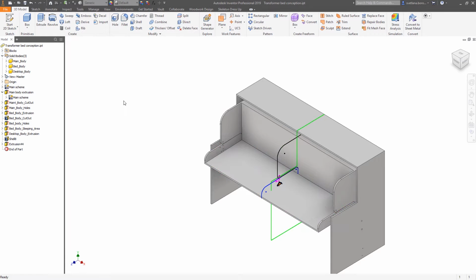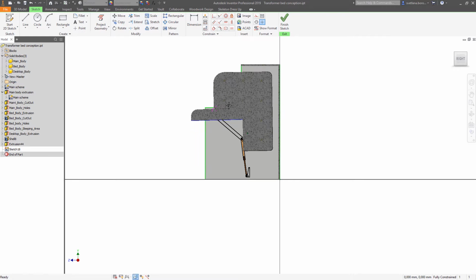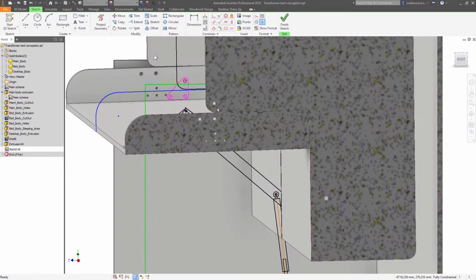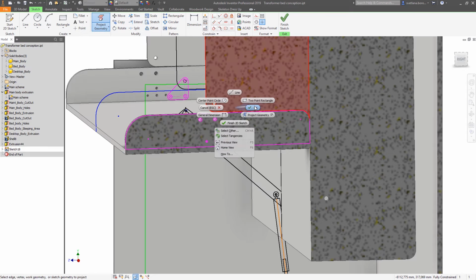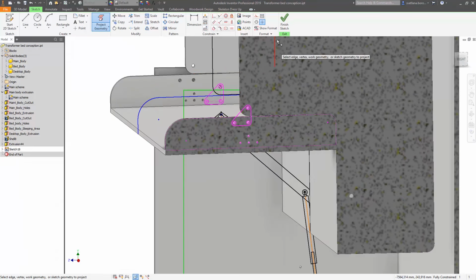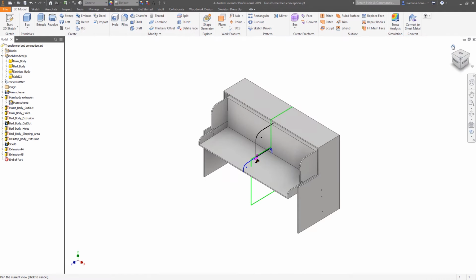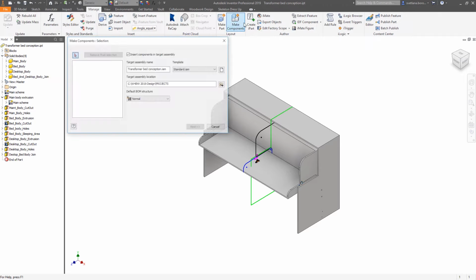reference geometry. And now we can use our sketch, project the geometry of joining item, joining element, define its thickness, and see if the components are not overlapping in 3D. If not, that's okay. If some overlapping is detected, we can do adjustment, define where those components must be placed. Once we have all the main blocks, new assembly can be generated.